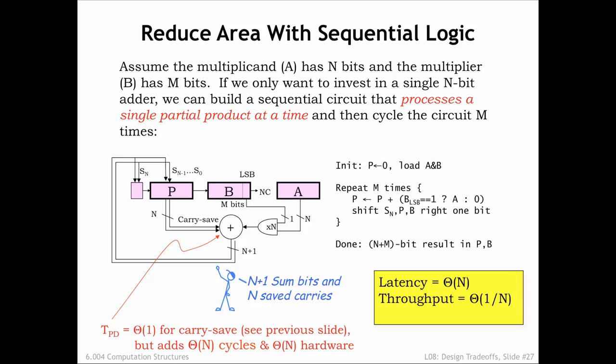The big change is in the hardware cost at order n, a dramatic improvement over the order n squared hardware cost of the original combinational multiplier. This completes our little foray into multiplier designs. We've seen that with a little cleverness we can create designs with order 1 throughput, or designs with only order n.